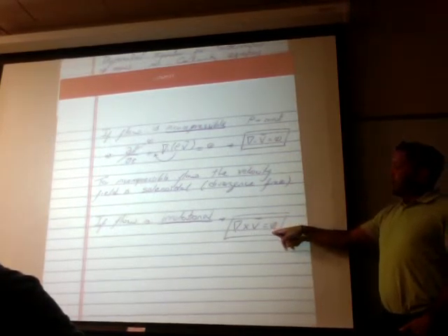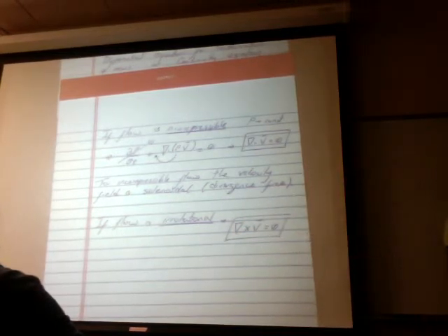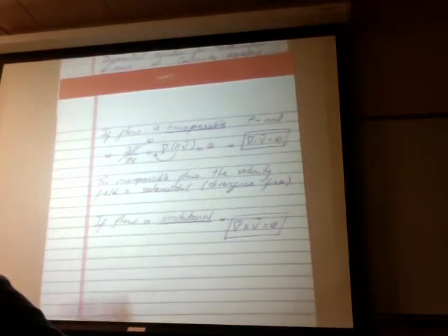In the case of irrotationality, this is a big assumption. Saying that a flow is irrotational is almost equivalent, it's actually equivalent, to saying that the flow doesn't have any viscosity, which is not ever true. But from the point of view of mathematics, this is the first attempt that people could use to actually solve fluid flow problems. Because the equations of fluid flow are very complicated. This is just one of the equations. The other three equations in Navier-Stokes are nonlinear, partial, and coupled, which makes them impossible to solve. So people say, well, why don't we just make some assumptions, some simplifications, like they always do, and see if we can get to an answer? And this is the first thing they could come up with.